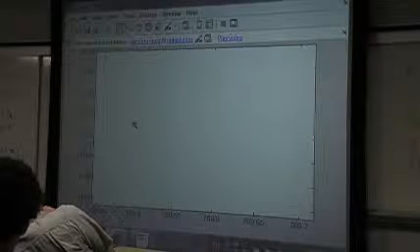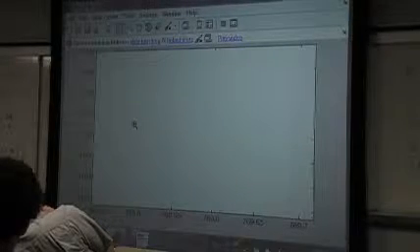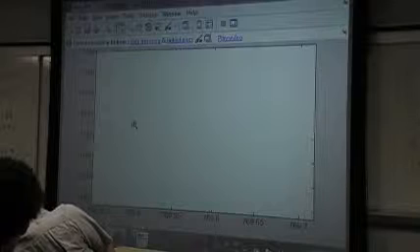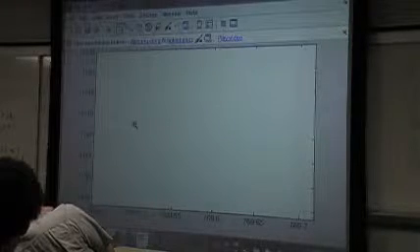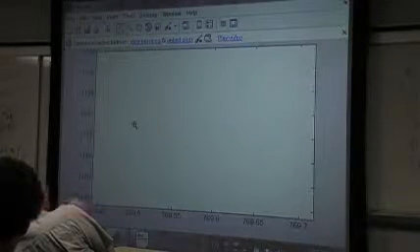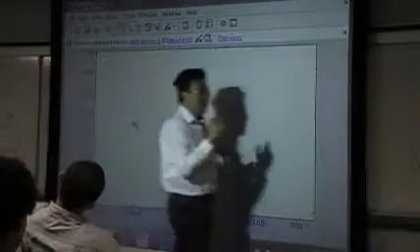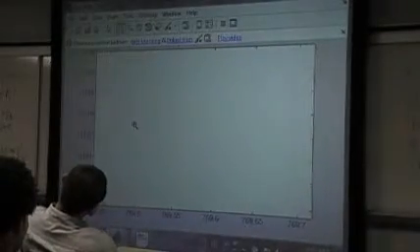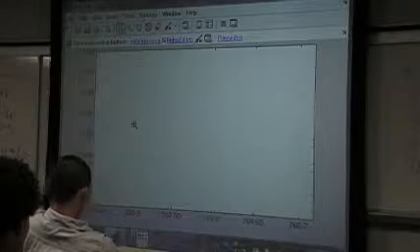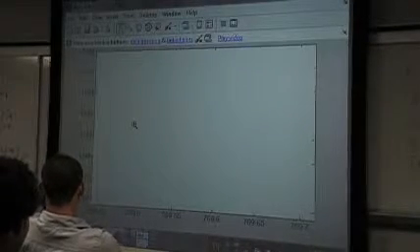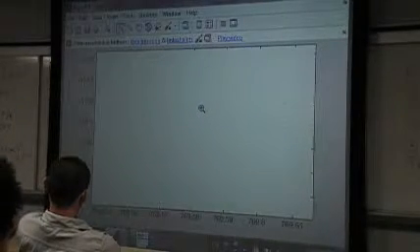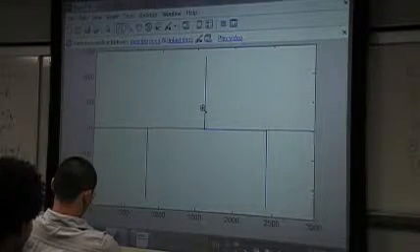It should be something like this. It is not vertical lines. It is also dynamic, but changes very rapidly. So it is hard for the ODE45 method to select the proper step size. That is why with the use of ODE45 we cannot get good results.